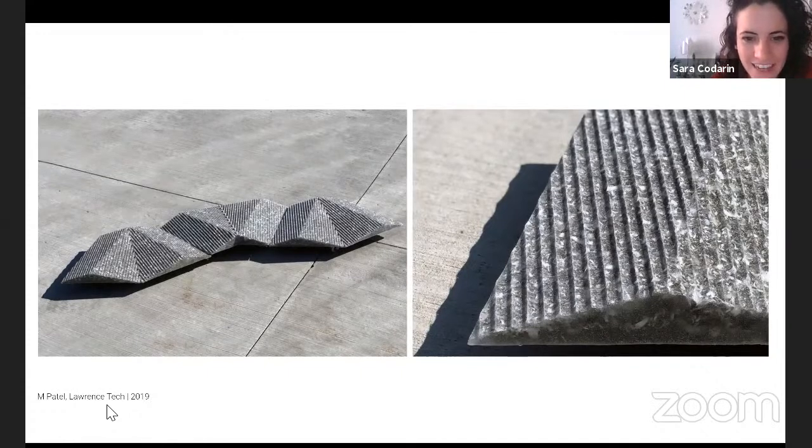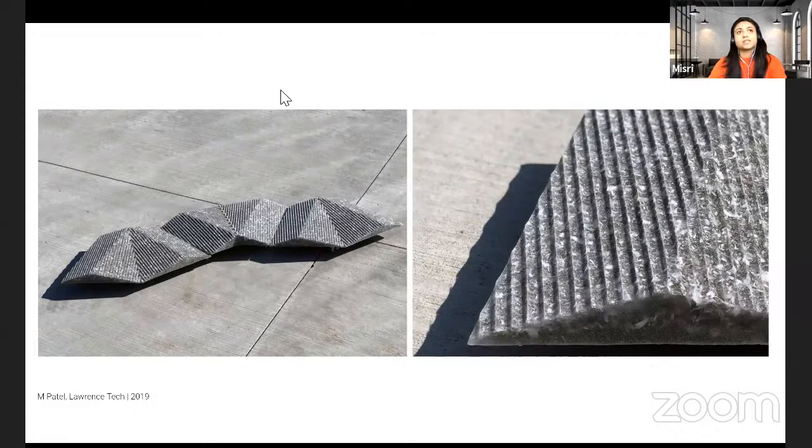From Hania: I had experience generating G-code for CNC machine woodworking. Each layer of the bullnose has to have a defined stepping going down in the material. I was wondering if the same situation goes for robot milling, or whether the robotic blade doesn't require going down in several steps, or it depends on the material and not the machine. It actually does stand true.